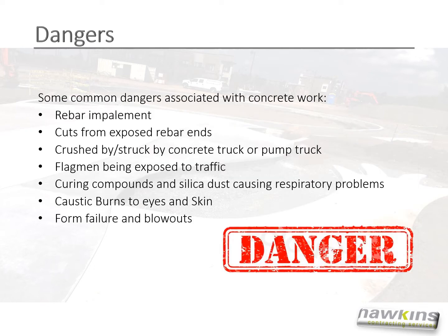Dangers. Some common dangers associated with concrete work are as follows: rebar impalement, cuts from exposed rebar ends, crushed by, struck by concrete truck or pump truck, flagman being exposed to traffic, curing compounds, silica dust causing respiratory problems, caustic burns to eyes and skin, form failure, and blowouts.